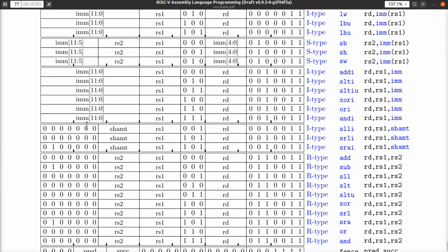It doesn't really have a func7 field over here, but because the shift amount can only be 5 bits of information, what we do is we abuse the fact that this I-type instruction only uses these 5 bits for the shift amount, and we sneak a peek down here in what would be otherwise a func7 style field to figure out whether we're doing an arithmetic shift or a logical shift, okay?